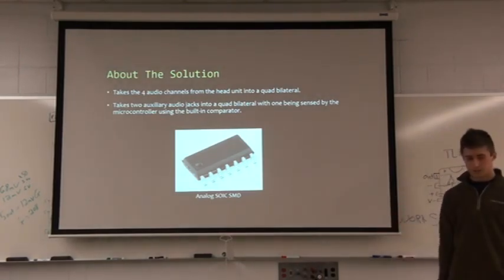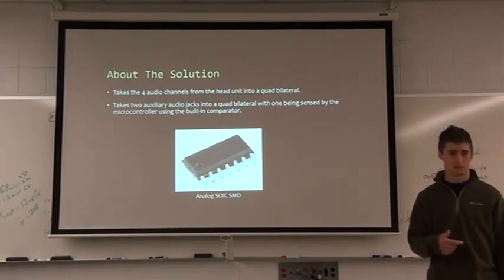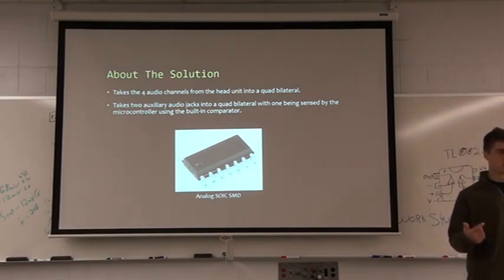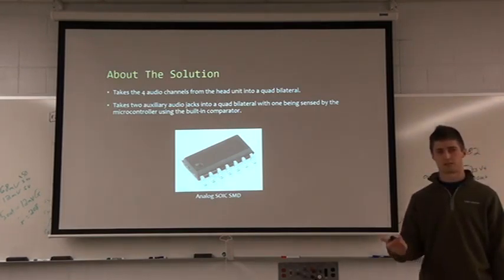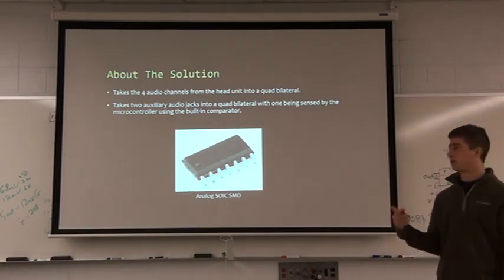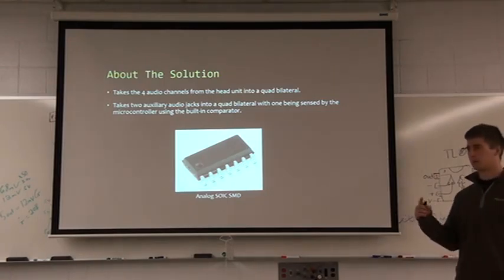The reason I chose the newer devices versus the older ones is that the gate turn-on voltage is above 2 volts, so I can directly take the microprocessor to each individual switch and turn on the switch and close it, so the signal passes through.